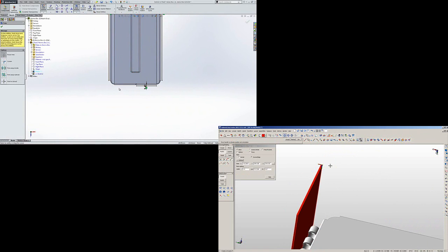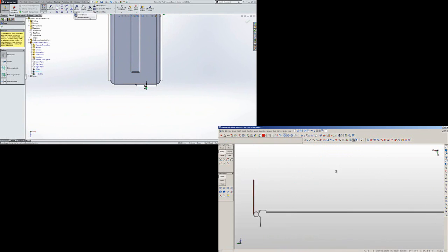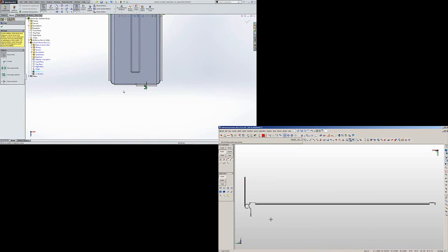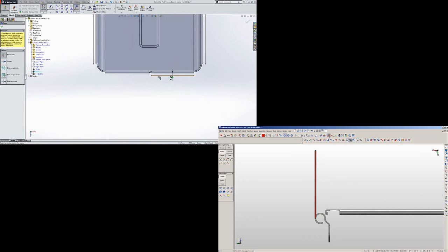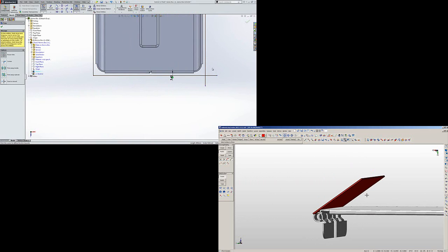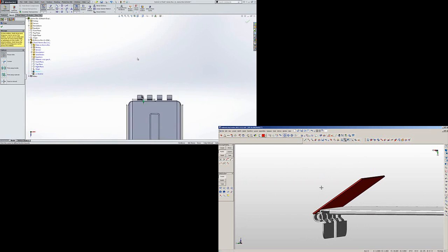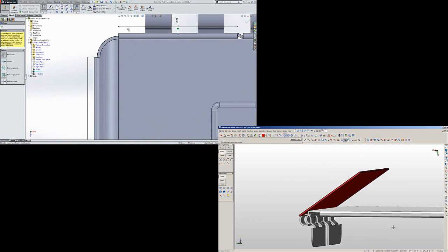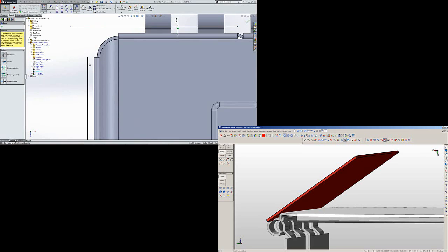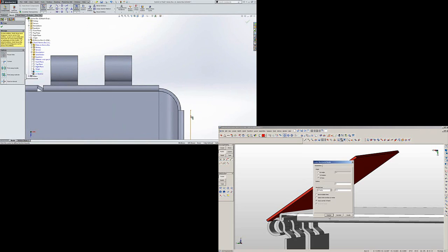We can select our trim entities. Now rather than selecting our extended entities, we can use our trim entities tool, but holding shift key down we can actually drag our entities across each other like so. Release shift, and now we can use our power trim. So nice and quick to create a closed sketch. So shift, drag, and then release shift and trim. Nice and quick.